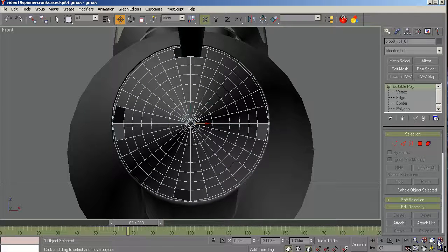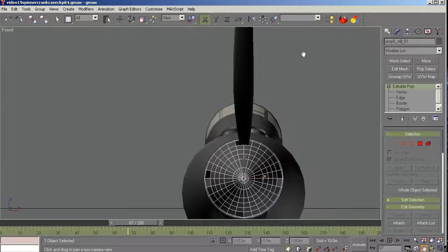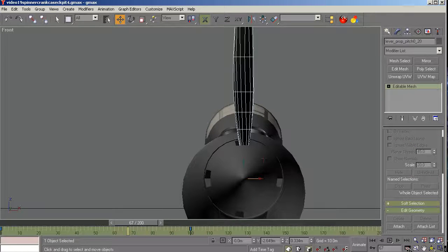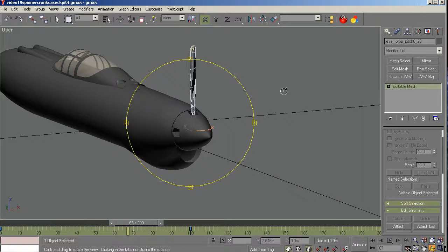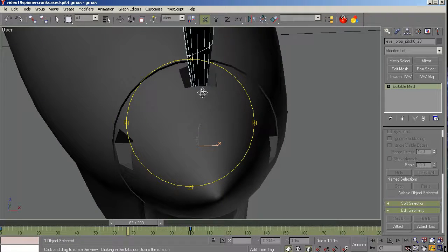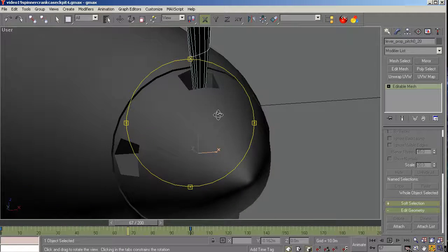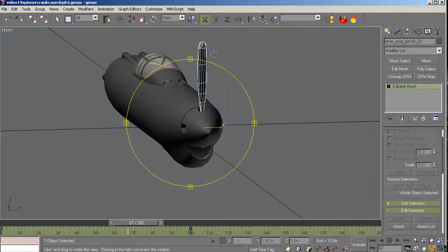So that's how I did that, and because of the time it takes to select all those polys, I won't do that, but I'll show you how to use the array tool to propagate the prop blade in place. In order to do that, of course, when you bring in a prop blade, which I borrowed from another project, it was kind of the incorrect length, so I had to change the length and skinny down the interior parts of it a little bit to make it fit properly. So I've got a proper 6 foot 1 inch blade here. Our diameter across here is 12 feet 2 inches.